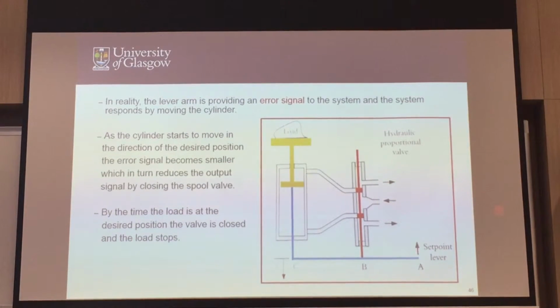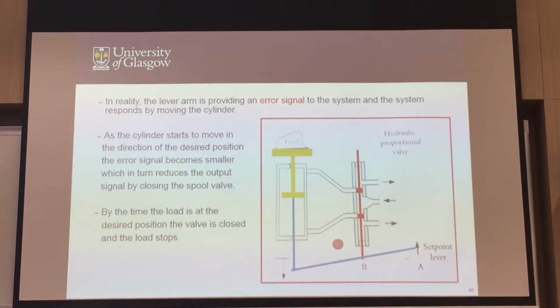Okay. So it starts with this. So over here, you will apply your lifting force. As you lift it, you can see that the spool will move upward. But because it's pivoted over here, you actually don't change much on this piston. And then this part gets energized. And then when it gets energized, you'll push down everything, including the spool because it's connected by this link over here. It'll go down like that.